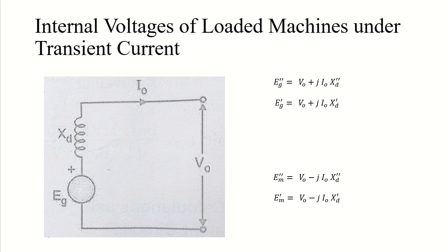The short circuit analysis, if you are doing it for the whole interconnected system, the synchronous generator and motor are replaced by their subtransient and transient circuit models, and all the other components of your network will not be changed, because those are passive elements of your system, so there will be no change in them. But because your synchronous machine, motor or generator, will be active components, you need to change them.